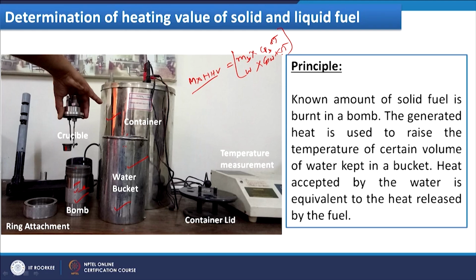So, if we ignore any other type of corrections, then this is the basic formula. Now, from this relationship we can get m_b Cp_b plus W Cp_w, multiplied by del T. This whole term is replaced by W, the water equivalent of the calorimeter, and this is the property of this material, what type of material it is, and in short the properties of the calorimeter.